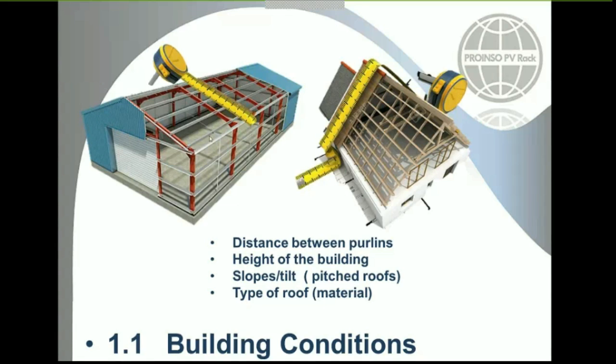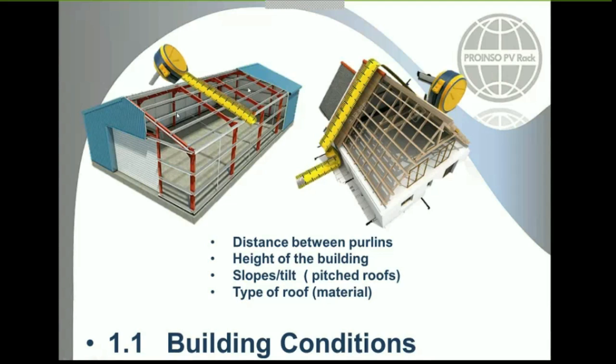As we are going to fix our structures to these purlins, we need a layout, and the architect of the building could give us all this information, because sometimes, depending on the wind loads, we have more or fewer fixings in our structure. In this case there will be no trouble, because you can place your fixings at any distance required.